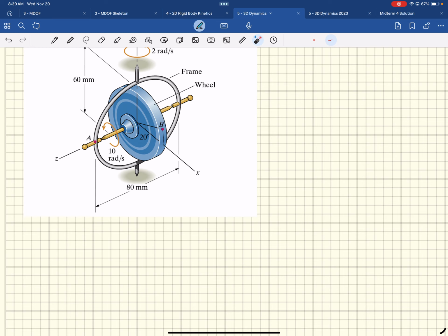But then for the omega that I use, I'm on the body, so I have to take into consideration that this is rotating, and the thing that it's rotating about is also rotating. So I'd have two components in my omega when I make that step. Same thing with alpha. If I was looking for the acceleration of point P, I'd have an alpha about the x-axis, because I've got a thing rotating about a thing that's rotating, and it's changing directions, so there's going to be an alpha.